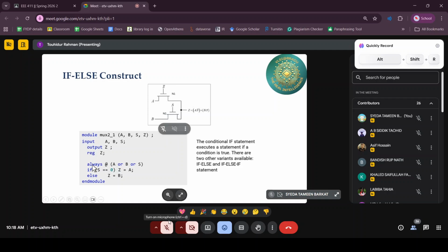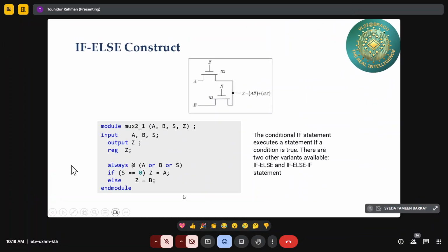Now, we're going to describe the behavioral model for the first time. This is the structure of the behavioral model. The data flow model uses assign, then a Boolean function. The structural model will be connectivity, and, or, etc. Or sometimes we can use a built-in function, or our own function, for the structural model. For the behavioral model, this is the structure.